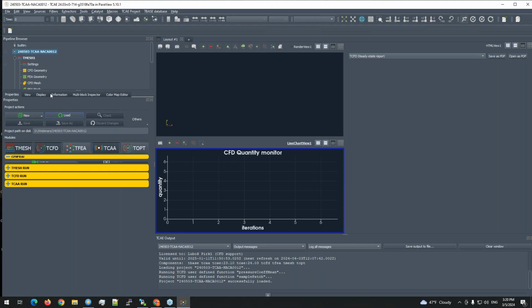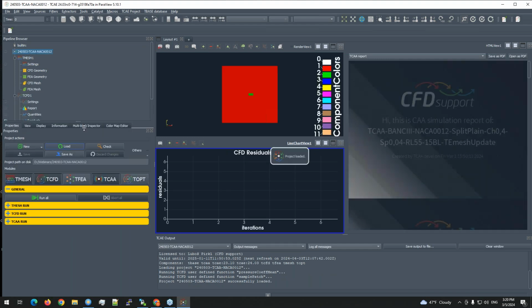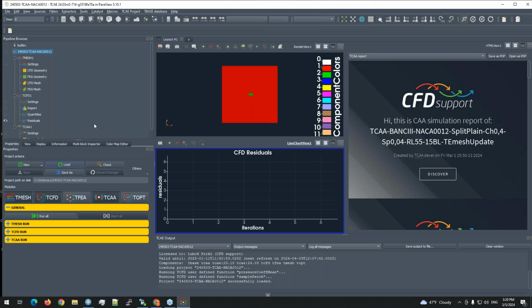First, the workflow consists of setting up nice and reliable CFD workflows. You can't start with acoustics without confidence in the CFD results, that they are giving what you need. And if you are really sure that everything works fine, everything converges fine, and the integral values are very close to what is expected, then you can go for the acoustic analysis.